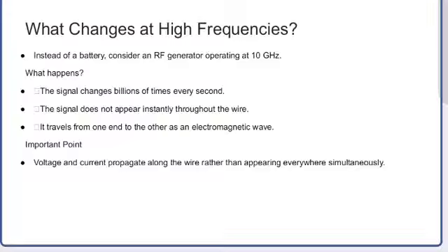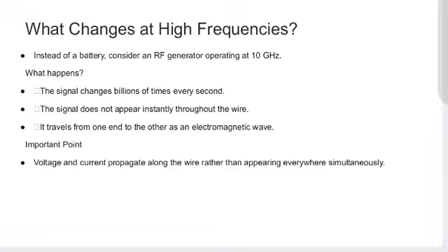That disturbance is equated to the flow of voltage and current in the transmission line. Just like the disturbance in the water, the voltage or current in the transmission line also flows through the line in the form of waves at higher frequencies.